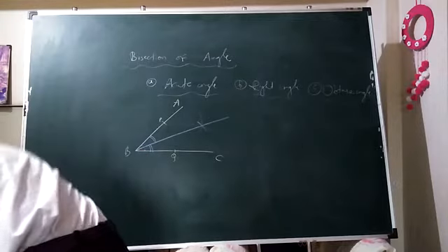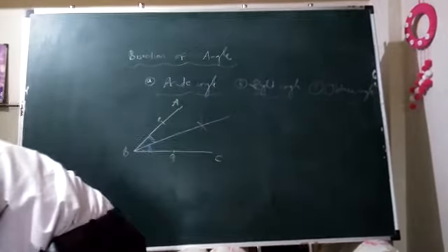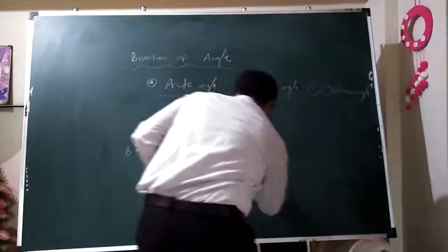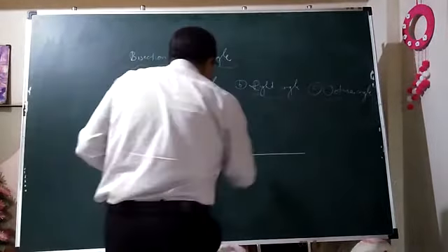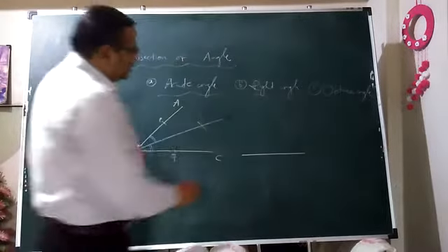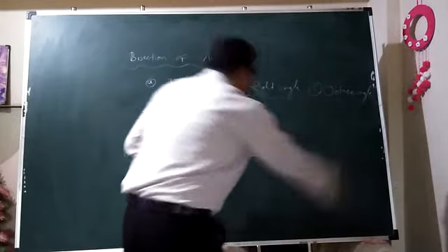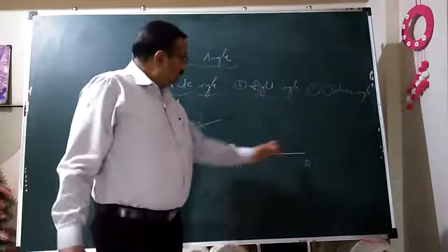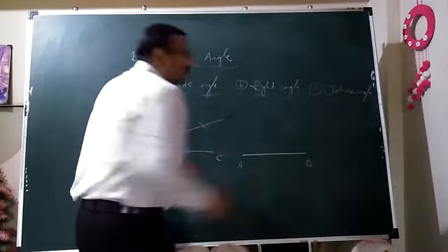Same is the trick for the right angle also. Okay, first of all, just for the sake of practice of the first construction method, we will construct a right angle geometrically without using a protractor. So what is the first procedure? Suppose this is a horizontal line AB. What is the first construction method? To draw a perpendicular line through the extremity of the given line. So through A only we have to construct one perpendicular line.